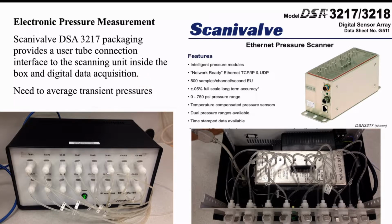Now, we'll get transient variable velocities in our wind tunnel flow with our flat plate because we're looking at a turbulent flow. And as a result, you'll get transient variable pressures measured on the scanning valve. That means that you're going to need to average those transient pressures so that you can get some average pressures and thus average velocity measurements from your performance.